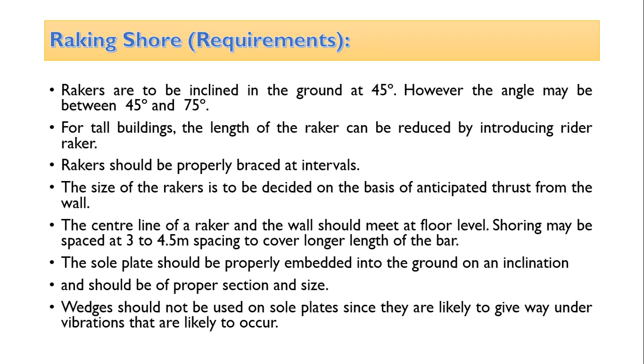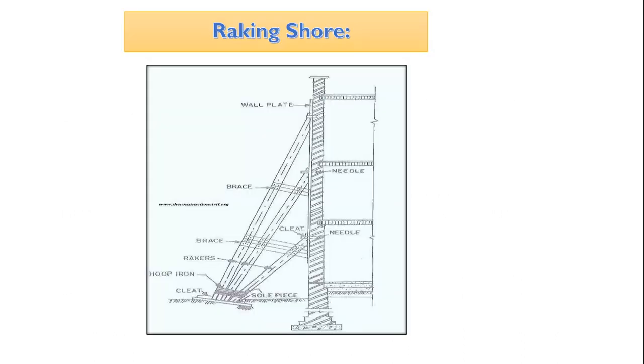Wedges should not be used on the sole plate. No wedges should be used since they are likely to give way under vibrations. If wedges are provided, during shocks they may come out, and in that case they will provide a danger. So these are the requirements of raking shore regarding the angle, the bracing, the support, and the wedges. Now this is the raking shore.